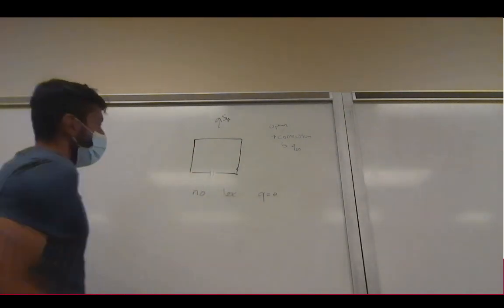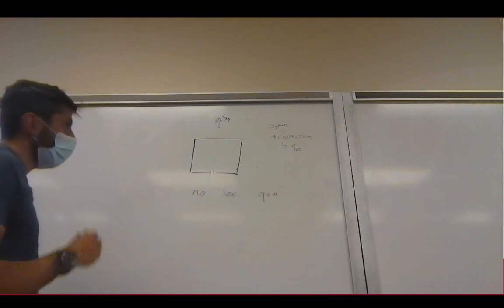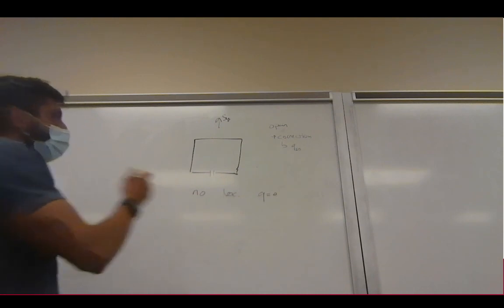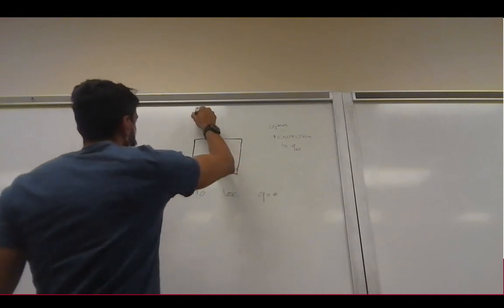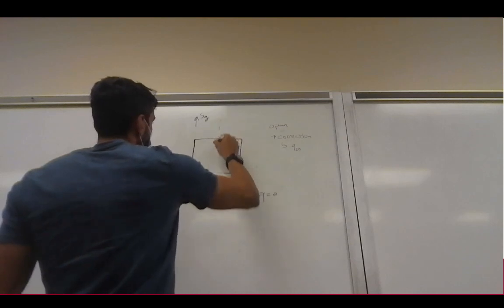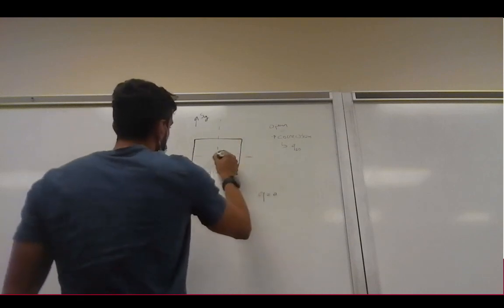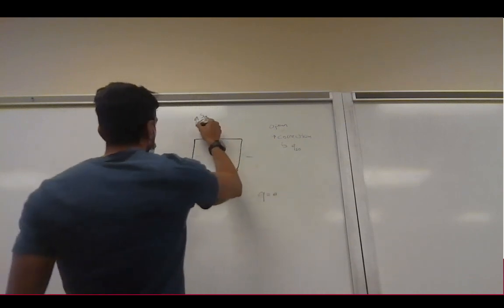So we calculate this as an open section. We do our simple shear flow equation again. To find this, let's assume that the shear force is located here as Sy. We choose a point, say the center of the beam, and we take the moments around this point.